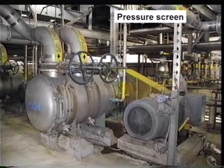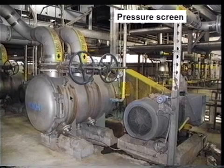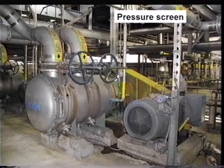So if there's plugs, and sometimes there are plugs, we can open up this cap, go in, clean out our screen, and fix the problem. Relatively easier than if this thing was in a vertical position and the cap was on the top.